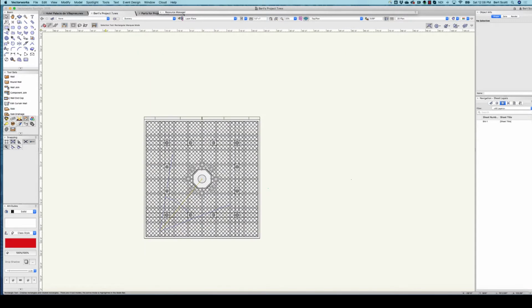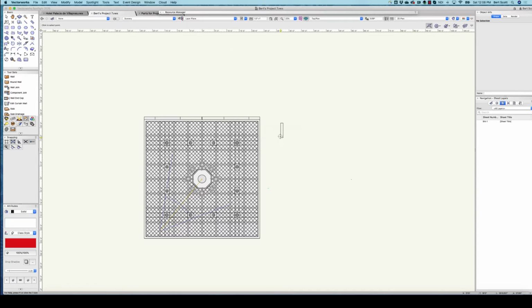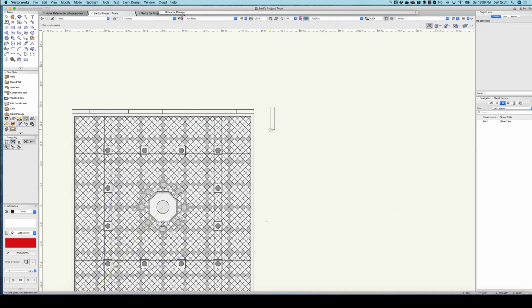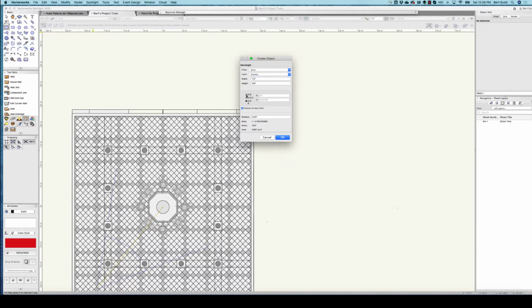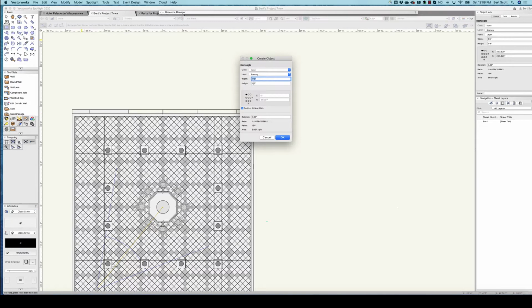So we'll draw a rectangle that is this time 12 feet wide and 5 feet 8 long. And we'll place it, let's do that again, and I'm just going to change the insertion to the upper left hand corner here. So 12 inches by 5 feet 8. And we'll put it there. And then the next one is 8 feet 10.